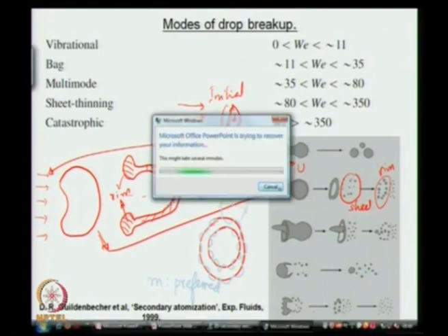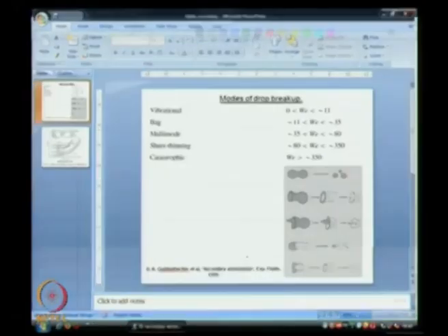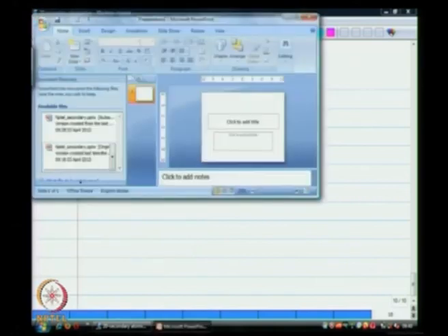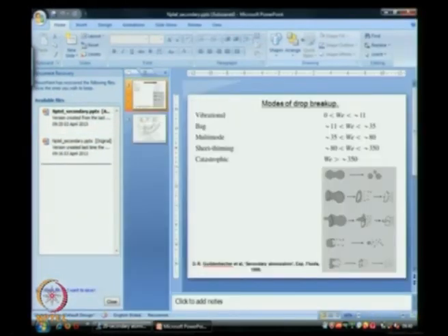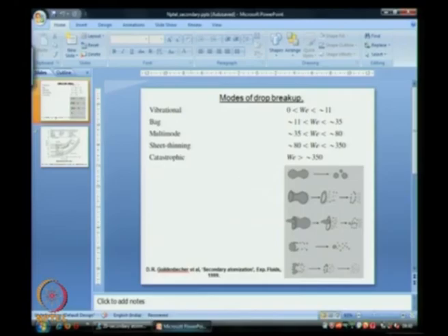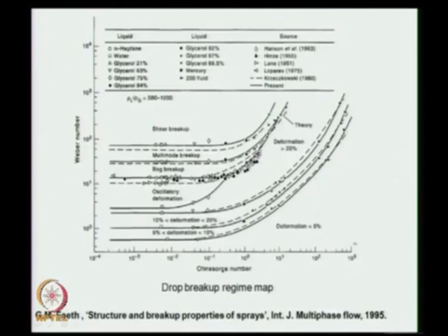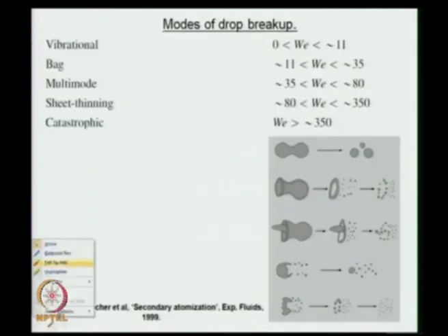And that particular value of m now tells you what the breakup looks like. So, if I look at the rim again, the particular value of m that you see causing the breakup of this rim determines the number and size of the drops formed from the breakup of the rim.